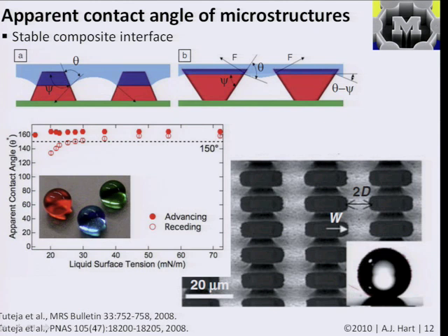And for example, in the Tuteja paper, it's discussed how these surface textures can be engineered geometrically and chemically to, for example, now repel oils, so liquids that have very low surface energies. And it turns out that what makes a difference is having a texture that's called a re-entrant texture, so something that basically can't be described by a function that would produce a hill like that. It basically cuts in over itself. So it means it re-enters as you go down.